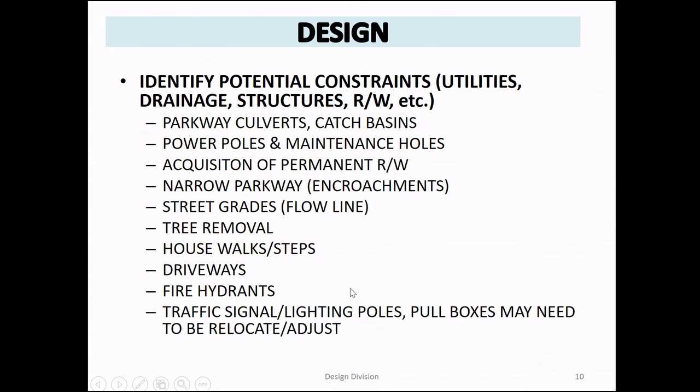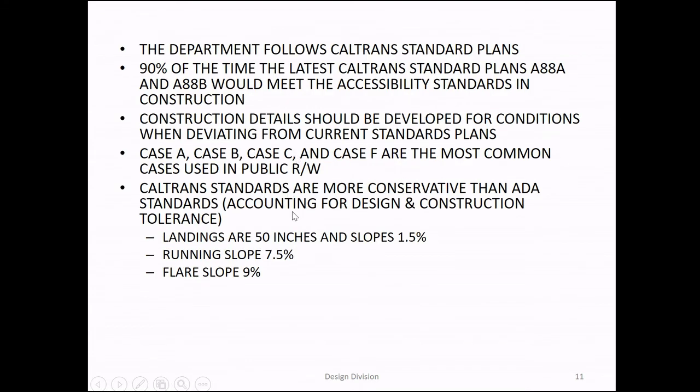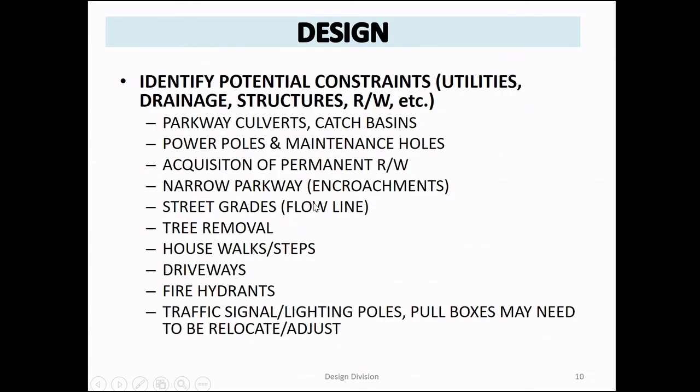So we're going to be scoping the access routes for accessibility. There could be a lot more things than the list that I have here, but make sure that you identify all the constraints that you have before you design your curb ramps, and that includes parkway culverts.